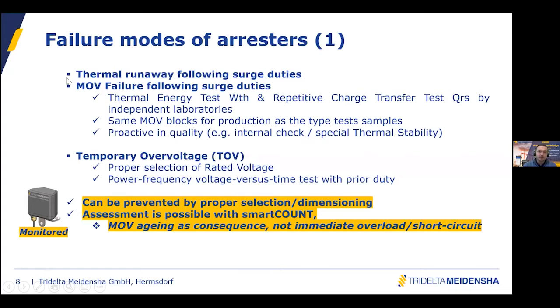A thermal runaway is a possible failure in relation to the energy rating of the arrestor. Also, an excessive charge transfer could lead to a failure of the arrestor. So normally, if the surge arrestor is properly selected and properly dimensioned by the manufacturers and properly tested, this should not happen. But in reality, the world is not perfect.